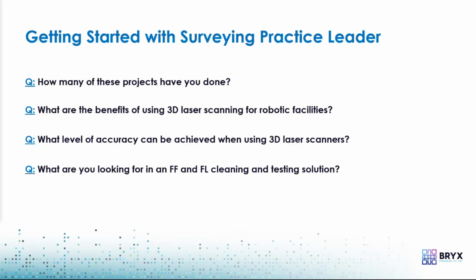There's the ASTM E1155 for floor flatness and levelness, and then there's the TR34. There are other types of products out there that have their own specifications, such as AutoStore and things like that. So for us, we want to make sure all those things are covered. And then for the output, again, back to the multiple clients, what does your client need to look at?